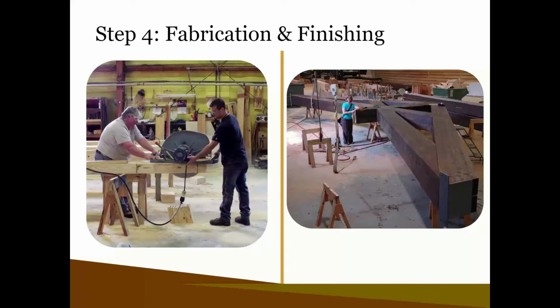Glulam is a material that's as fully finished and as fully fabricated as possible within the manufacturing facility. So we're going to do all of your bolt holes. We will do all of your angle cuts. If you are using knife plates, we'll do the kerf cuts. Whatever needs to be done, we're going to do as much as possible in the facility.